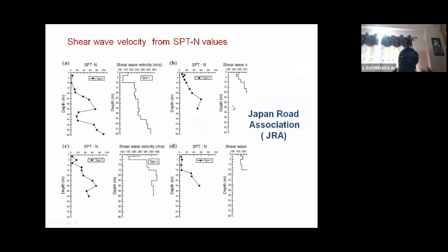And we wanted to have the standard penetration test data or stiffness of the soil in all these locations. And we collected this data. These are all standard penetration test values. And we want for our analysis what is known as the shear wave velocity. Shear wave velocity has to be measured in the site. Nowadays, facilities are available to measure the shear wave velocities right from the ground surface to an extent of 100-meter, sometimes even 200-meter. But as that facility was not available at the time, we back calculated from the available standard penetration test values.